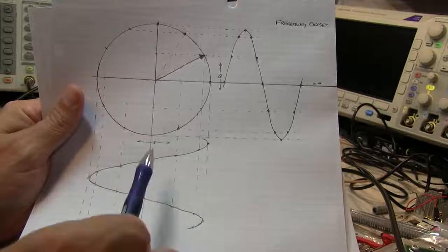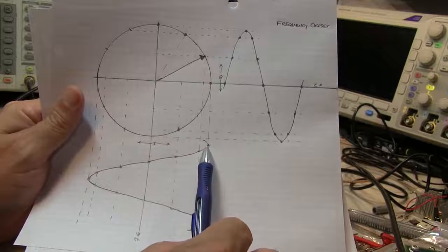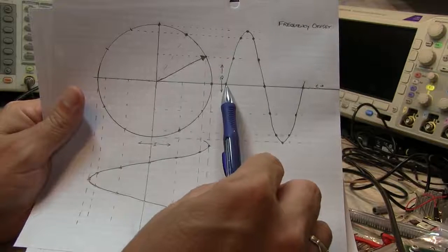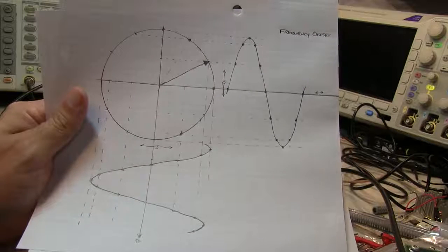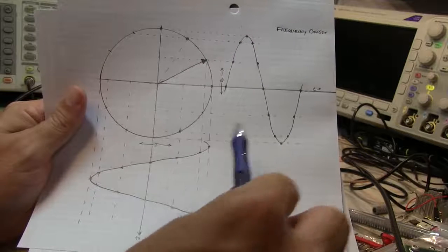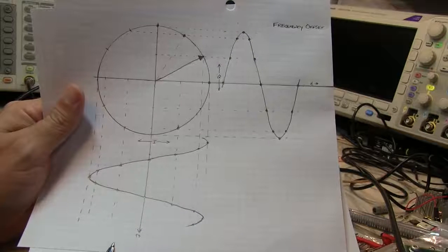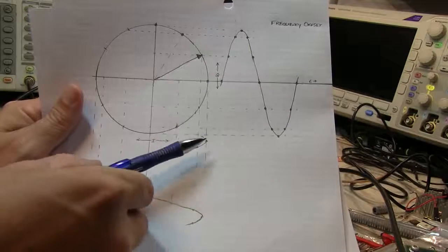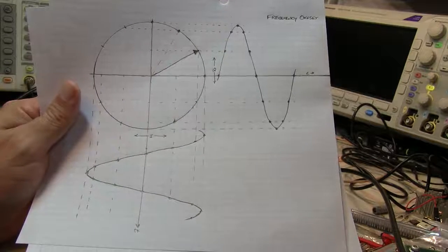The other thing that you'll notice is that these two sinusoids are also in quadrature. Where we started off, this is essentially a cosine wave starting at the peak, coming down and going around, where the Q is more of a sine wave starting at 0 and going around. So really a frequency offset is represented in the phasor diagram or by the IQ components as a pair of quadrature sine waves whose frequency is equal to the frequency offset. And depending on which one of these is leading, which one is essentially occurring first, dictates the direction of the frequency offset. So let's take a look at those signals.